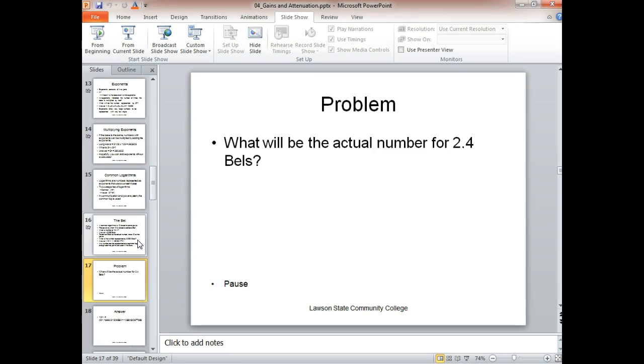They were close. That's what I like about that 0.9, where they did all the math. You can take your input RMS multiplied by 0.9, and you get a pretty good idea of what the output of your unregulated, unfiltered power supply is going to be. It's going to be a little higher than what you're actually going to measure because they didn't consider the diode drops and all that other kind of stuff.